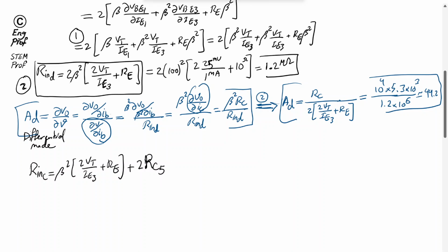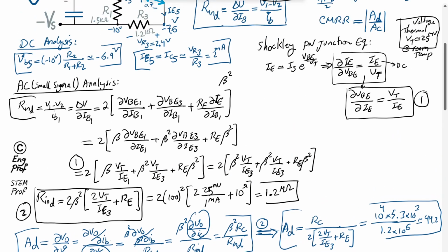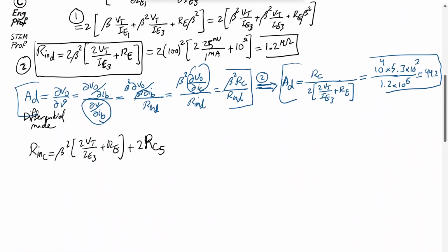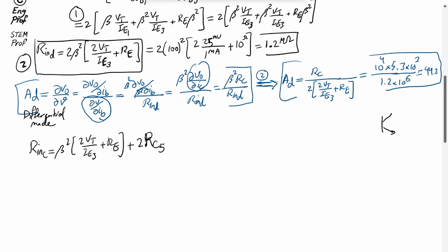It requires a little bit of time, but it's well known that when we have a transistor like this with the emitter grounded, then the equivalent resistor observed from the collector is simply RO of the BJT.